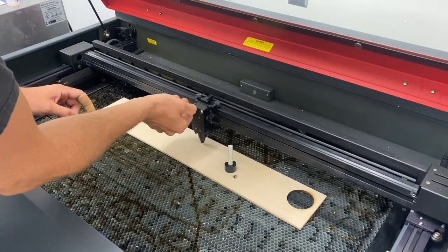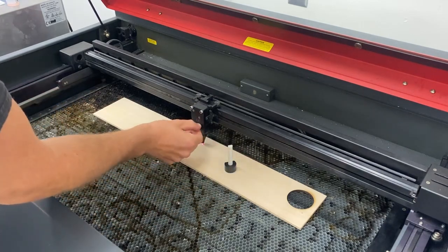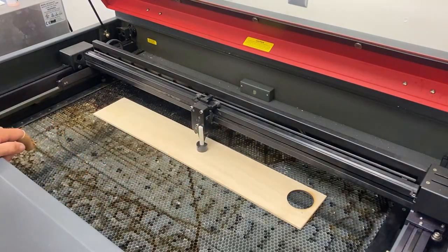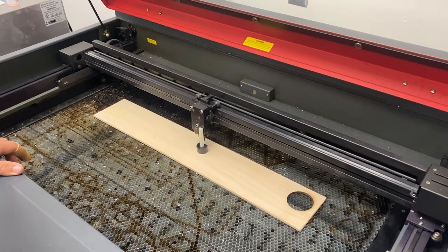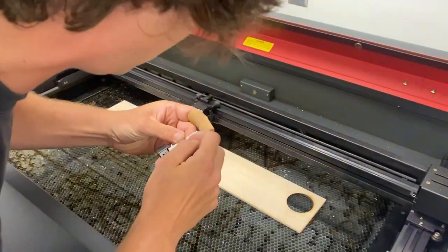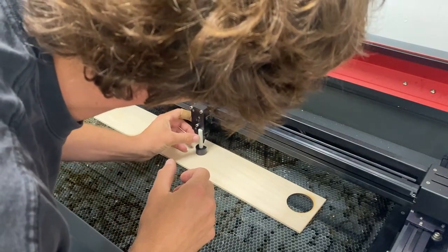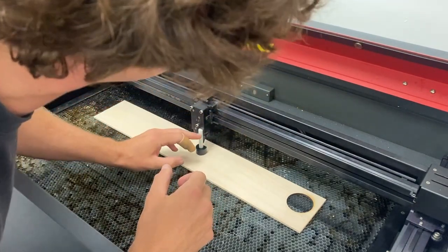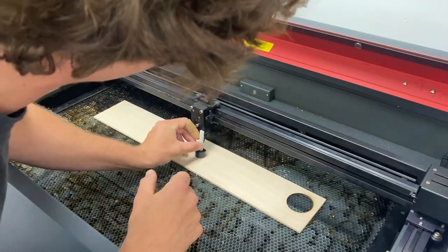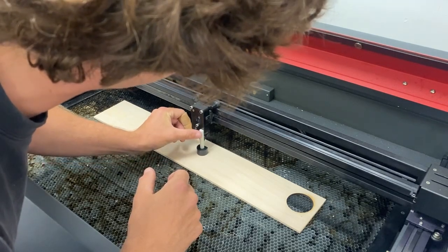Okay. Now this is kind of out of shot, but it's going to be helpful so that you see what's happening. Basically, we have a Z or a table height adjustment. So that's a Z. Basically, there are a couple buttons on the machine with a Z and an up and a down. So what I'm going to do is I'm going to bring this guy all the way down. Okay. I'm going to bring it down such that the little notch is below the lip. Okay. And then what I'm going to do is I'm going to set it up against there so the flat portion of our probe here is up against the bottom there.